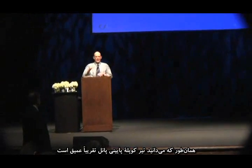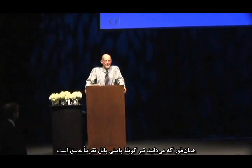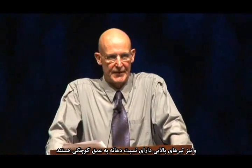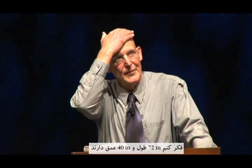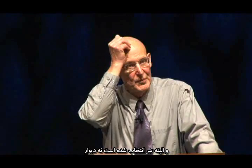Even though the bottom coupling beam was quite a deep coupling panel, and even the upper beams were relatively small span to depth ratio. I think they're 72 inches long and about 40 inches deep. They're still pretty deep. But I still chose to use beams, not walls.